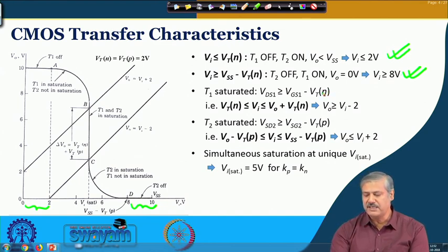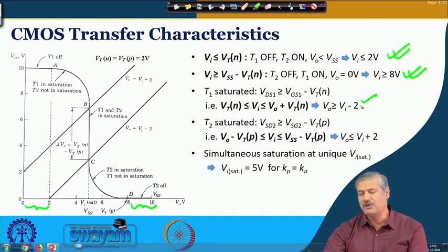So this particular case, when you map it to the corresponding voltages, V naught is your VDS and VGS is your Vi, okay, and 2 volt is the threshold voltage that we have considered for the NMOS, also for the PMOS.